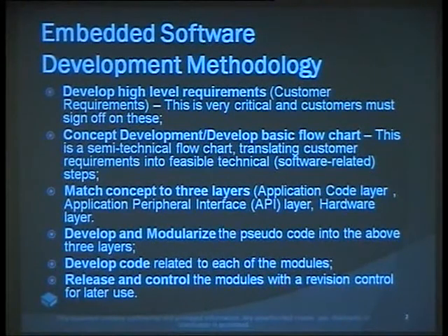You have a pseudocode developed, and when you do the Pspice simulation, you also have a pseudocode developed, because in the Pspice simulation, how the signals are flowing, the microcontroller is going to act the same way. So you have to use the whole Pspice model, the PI loop, the normalization, all of that is done inside the microcontroller.